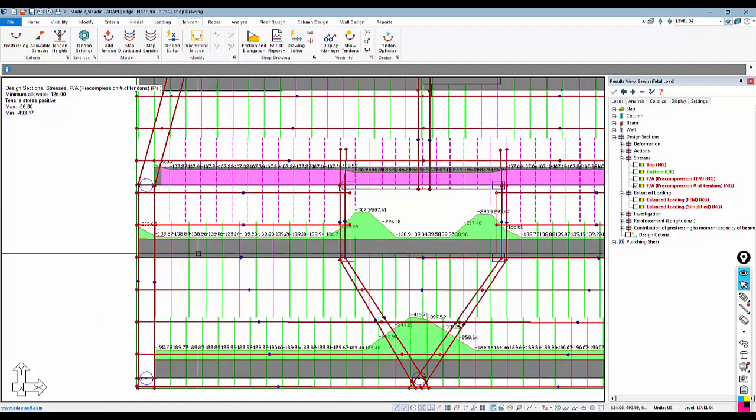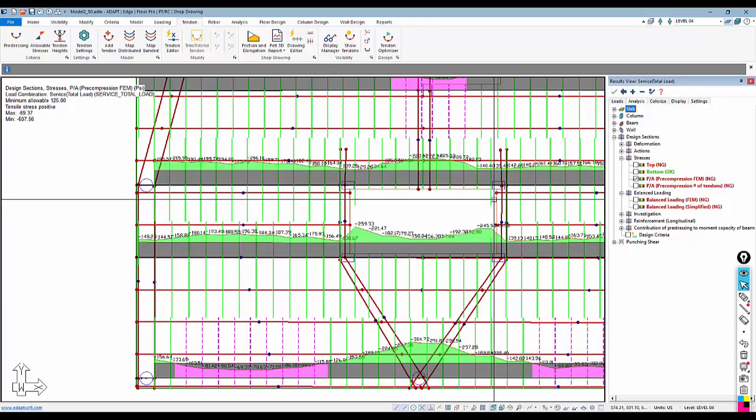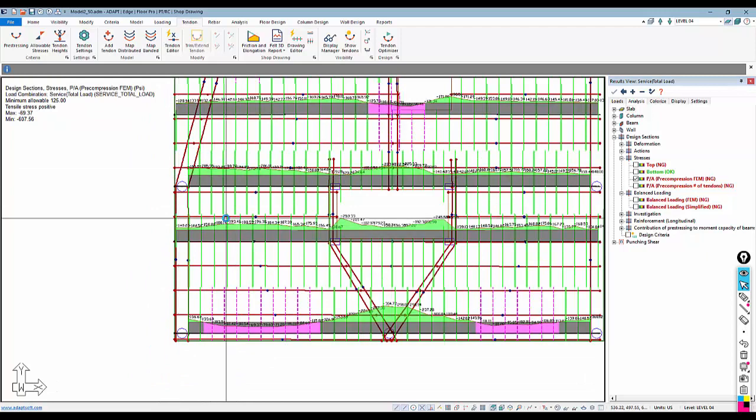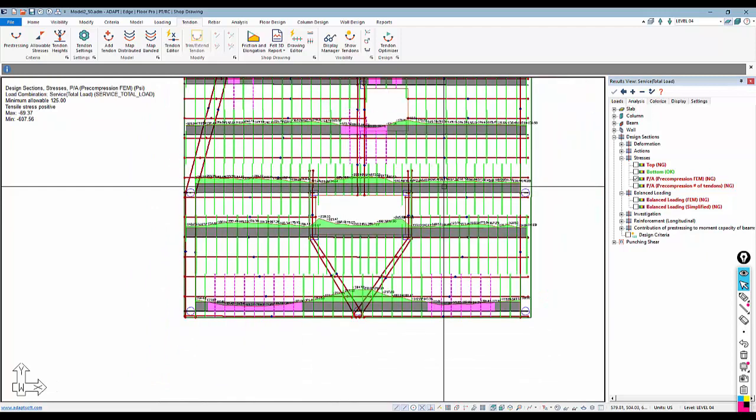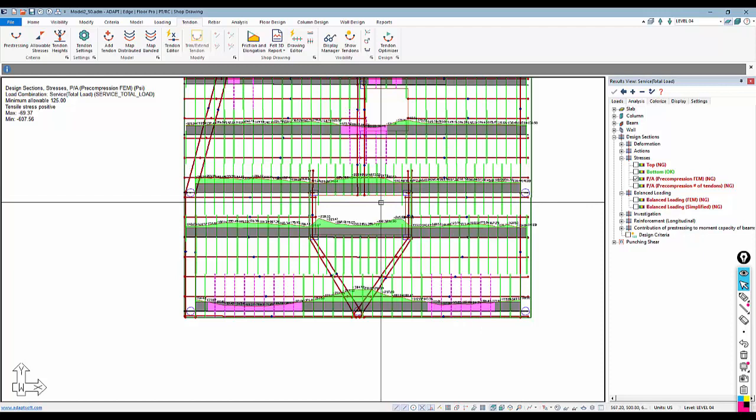The other approach is to use a finite element based approach, where we use the axial force in the plane of the slab to calculate the force over the area. And you'll see when this is low in this pre-compression number of tendons check, it actually might work in FEM. So this is the FEM result, where this curve is based on the axial force, which could be subject to restraint loss due to position of tendons, position of supports, releases, the actual fixity or boundary conditions for the supports, and so on.